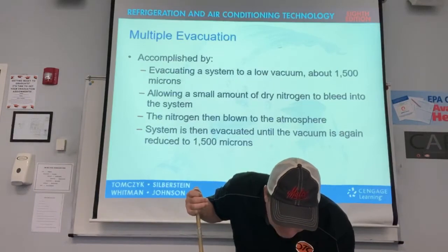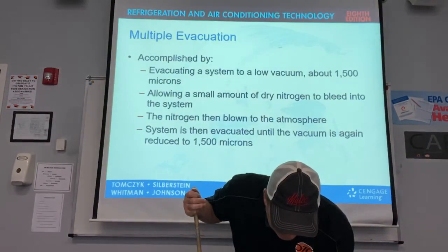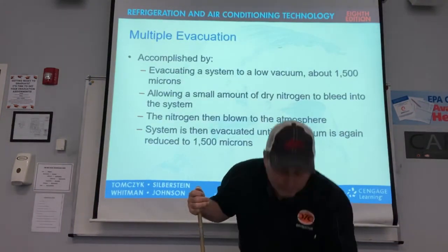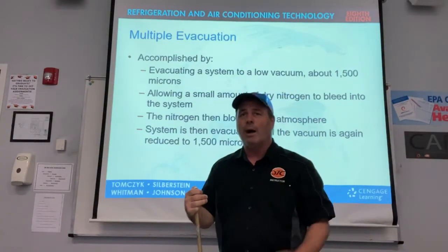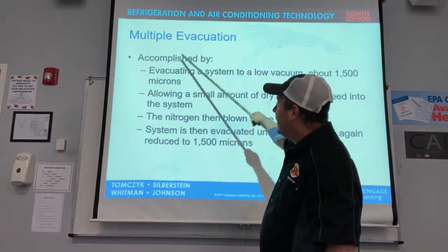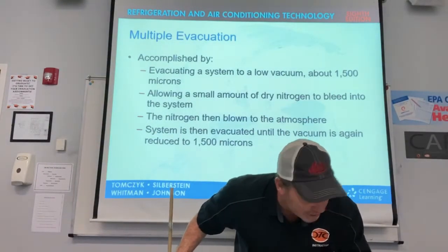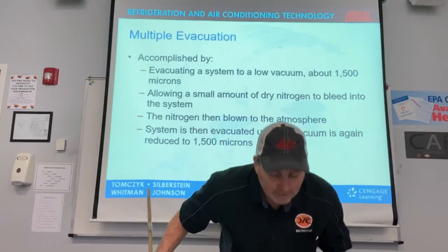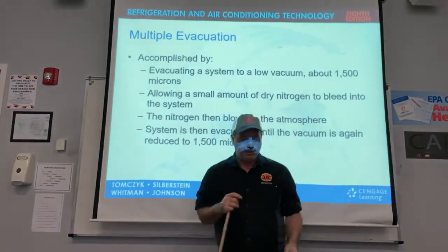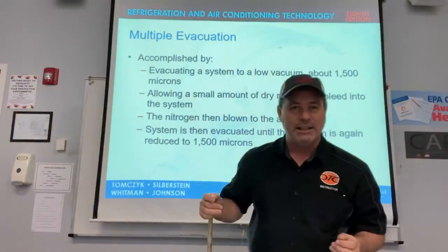The following is a detailed description of a triple vacuum, the latter being performed 3 times is called a triple vacuum. Doing it twice is a multiple. But that's a really good vacuum if you run a triple like that. Breaking it with nitrogen, that's how you do that. Now on 209, what did we say? If you look on picture 209, leak detection.